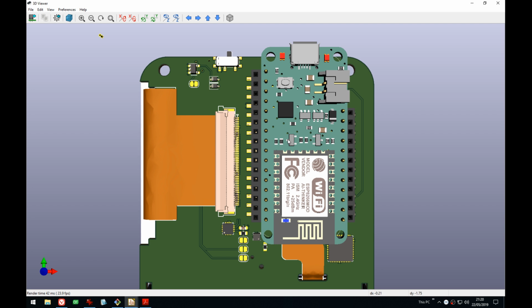So you search for that. I usually use Mouser and its filtering. Exactly. So first voltage, then you have to know the ballpark range of how much current you're going to need. I mean, you could go just 3 amps and that's enough for everybody, right?